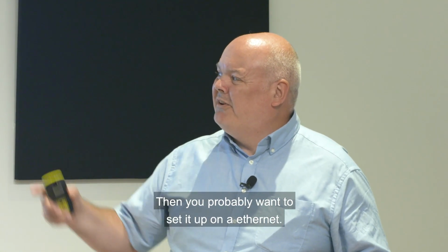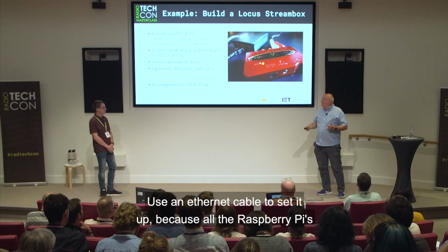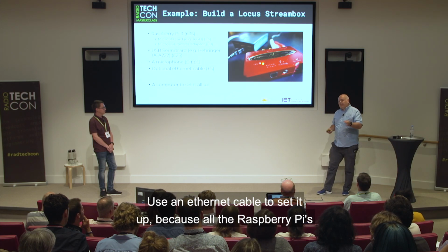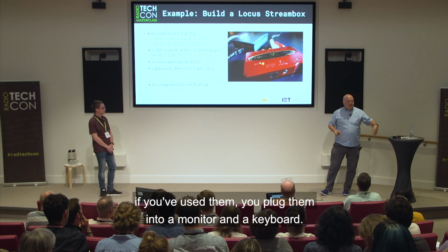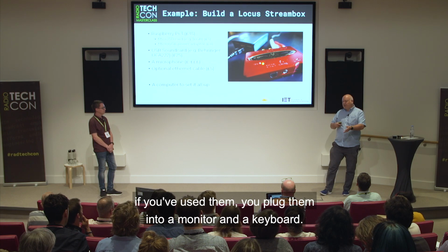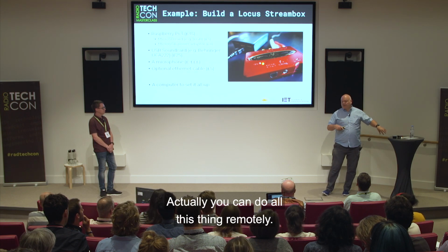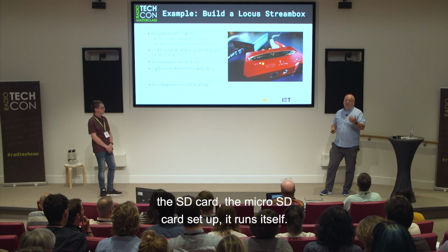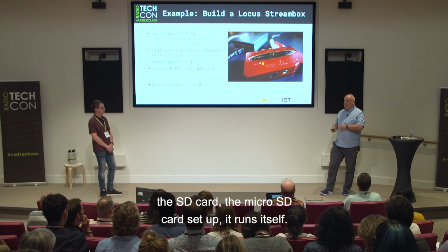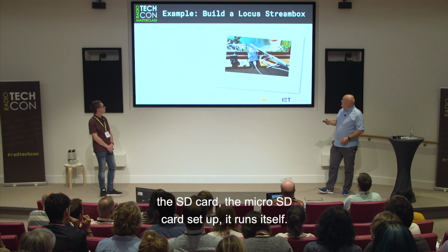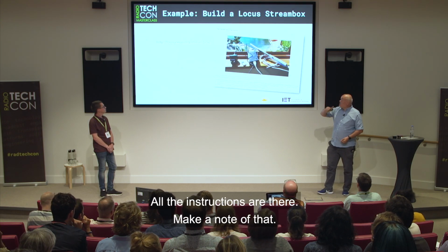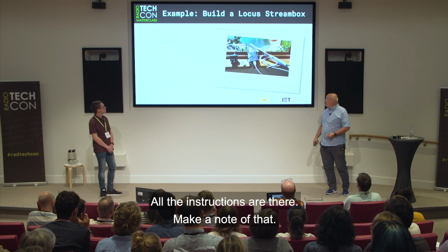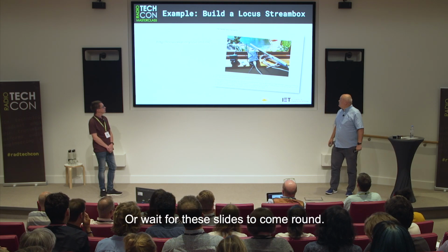And then you probably want to set it up on the Ethernet. Use an Ethernet cable to set it up, because all the Raspberry Pis, if you've used them, you plug them into a monitor and a keyboard. Actually, you can do all this kind of thing remotely, because the great thing about this little setup is once you've got the micro SD card set up, it kind of runs itself. All the instructions are there, so make a note of that. I'll wait for these slides to come around.